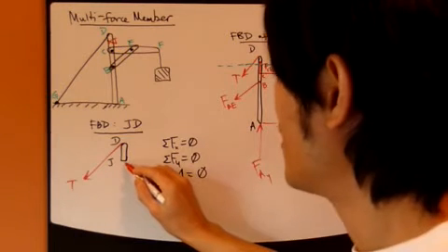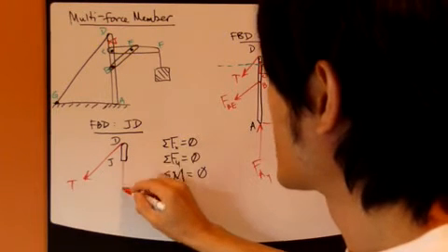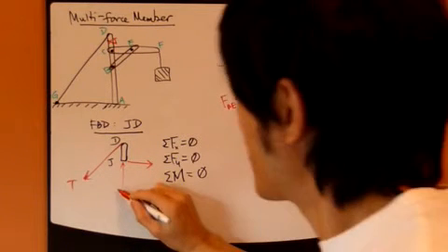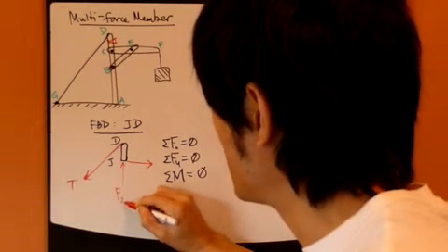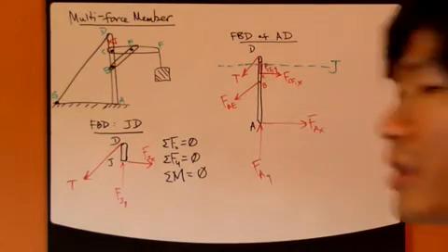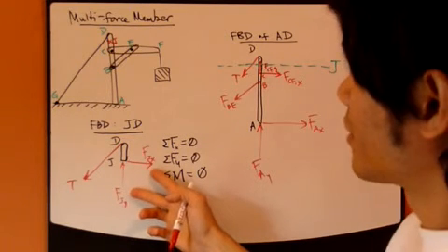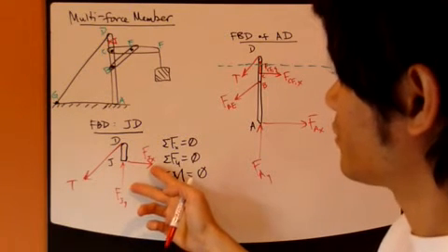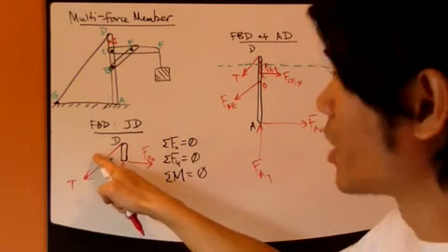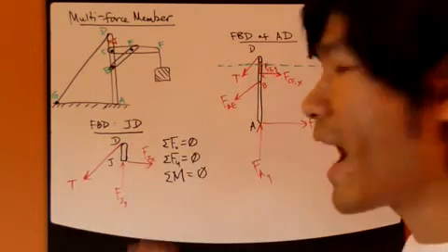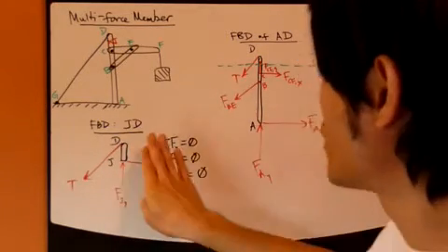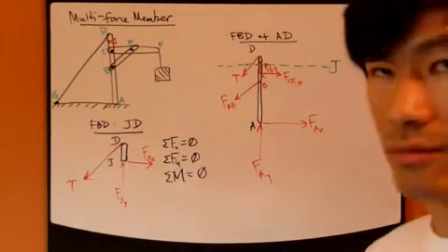There has to be, therefore, two forces at J. Let's call them F_Jy, how about that, and F_Jx, the x component. So these two guys will counter this T, this tension force, just so that this piece would not have any translation. It would not move to the right or left, or up or down.